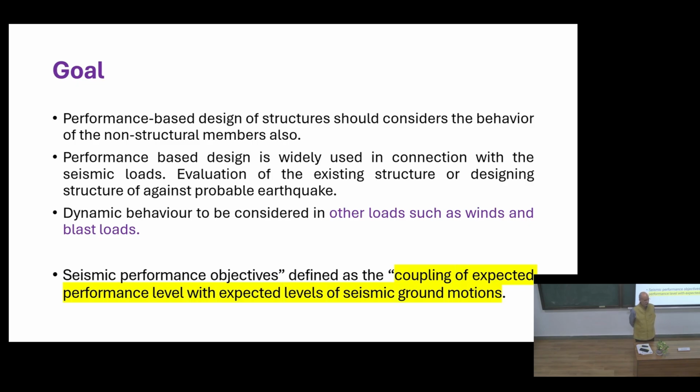The performance-based design means that two things come into the picture: the structure in total, and the material which you use. The performance of the material becomes equally important. So if you have a glass building, that is dangerous. Nowadays, many glass buildings are there. You look out for the green building concept also, but from a seismic, earthquake-resistance point of view, they are very sensitive, because if the glass falls from a 10-story building, we can understand what happens.